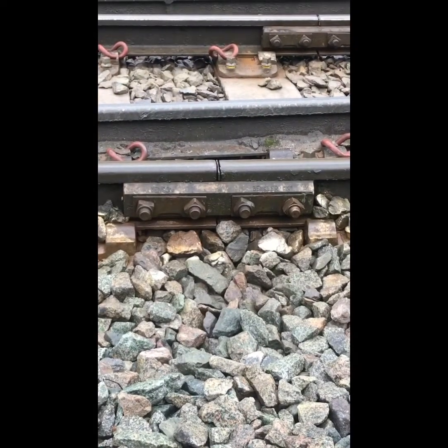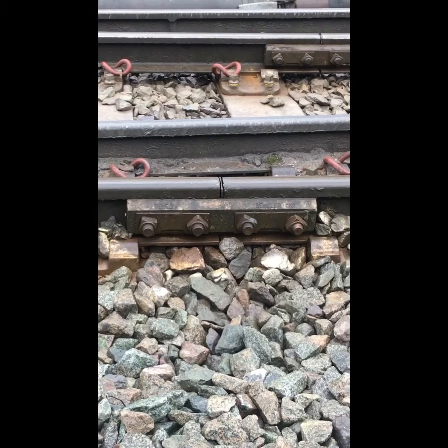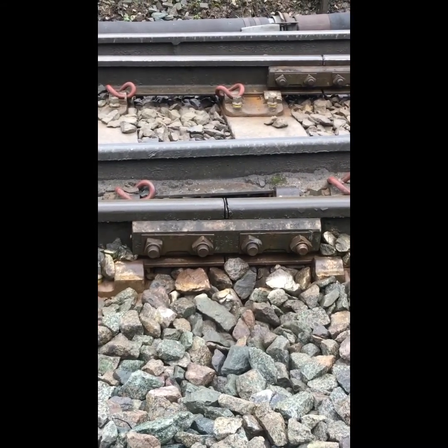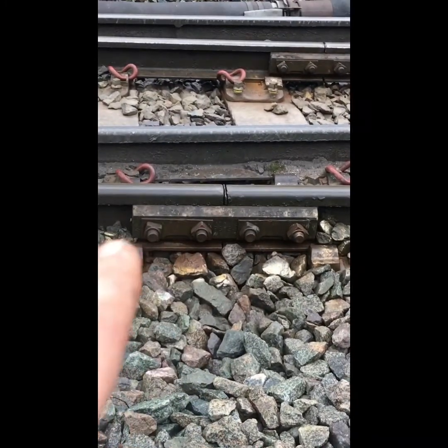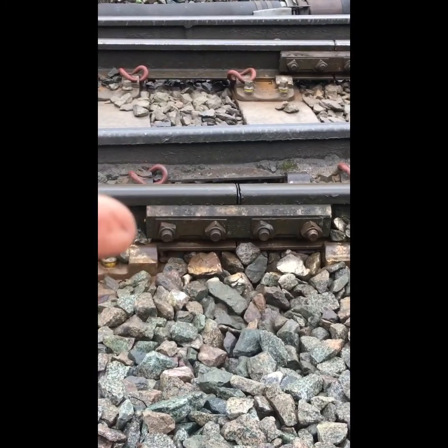Insulated block joints come in many different types. This is a 4-hole. You can have a 6-hole pre-made one. This is a 4-hole Benkler. Benklers allow you to take the block joint apart. They come as 2 side plates, one on this side, one on the far side, and then you have a set of insulations that go just inside on the plates as well, and bolts that then fit through.